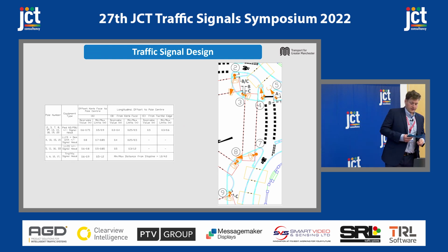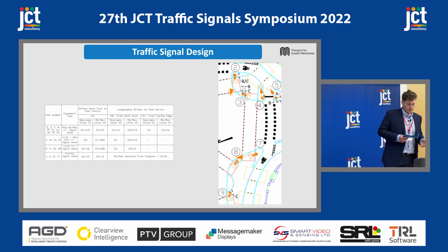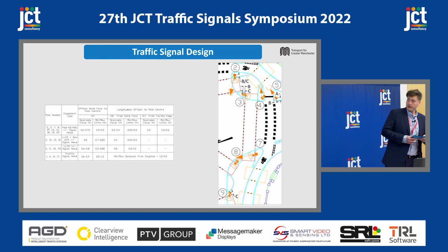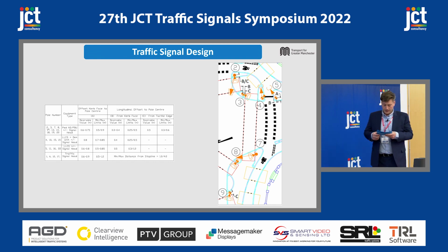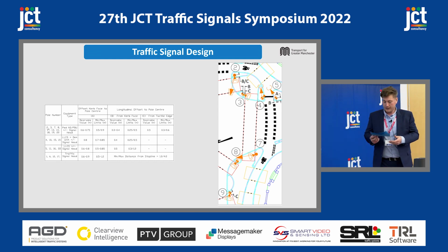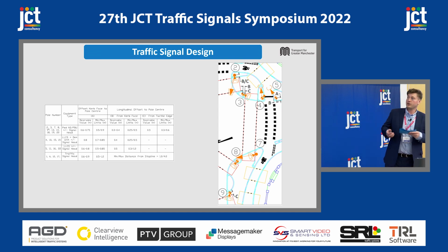So here this table shows the ideal positions of various traffic signal poles. Each type has a varying position relative to its surroundings. For example, as you can see on the drawing, say pole 5, for instance, is solely a low-level cycle pole on an island. So that has a specific distance from the carriageway curb line and an offset from the cycle track curb line.